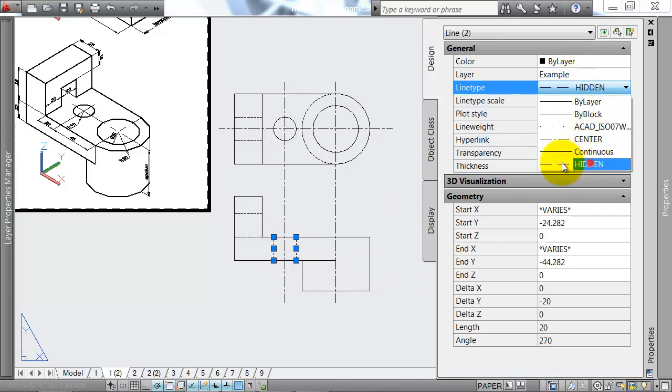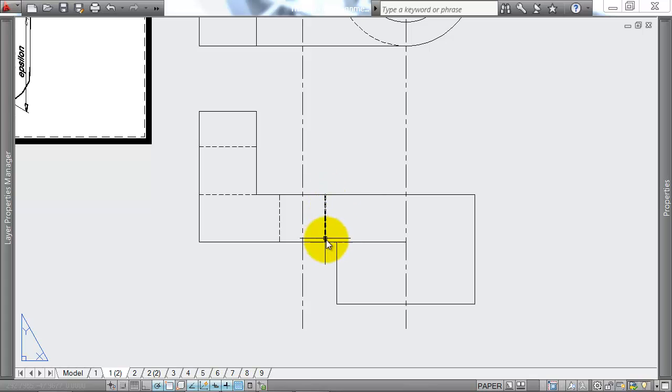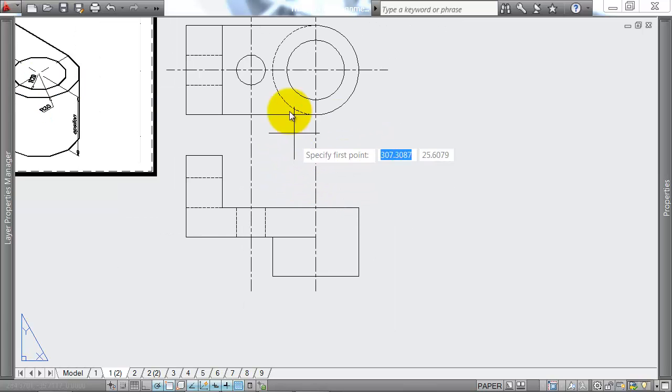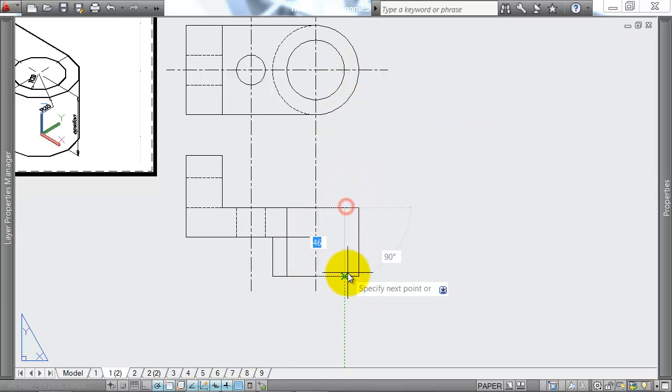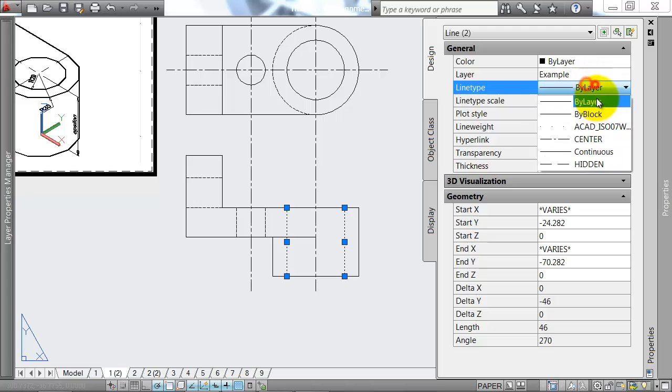And the center line tells us that this hole isn't square. So this hole up here, we've got two center lines. These are actually almost identical. Two hidden lines, two hidden lines. This one is representing a square feature, this one is representing a circular feature. The only way that we can tell that in this view is that this hole, this one here, has a center line and this one here does not. The lack of a center line means that this is a square hole taken out of there. The only other two hidden lines we need are the hidden lines for this circular hole, and they go the whole way through the shape.